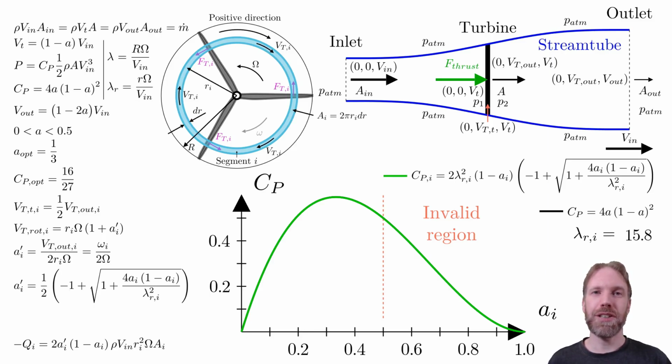Let the tip speed ratio decrease. When we have reached a tip speed ratio of 5, we can see a small difference between the two. Decrease the tip speed ratio to 1. Now we can start to see a notable decrease in power coefficient due to wake rotation. Let it go down to 0.1. Here the power coefficient is significantly lower.